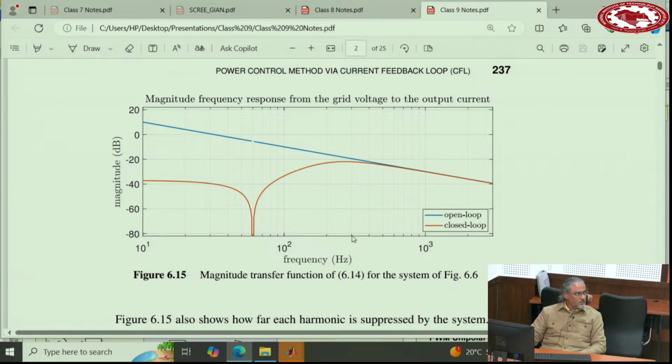300 means the fifth harmonic, which is often the first harmonic that is there. So you see open loop and closed loop are already at the same point. That means this controller does not help with harmonics, does not mitigate the harmonics. What it does is make sure that at the fundamental frequency, the grid voltage as a disturbance is removed, because we put a resonant controller there to follow the reference. That follows the reference and also removes the grid voltage as a disturbance, even though we put a feed forward anyway. The feed forward takes care of removing that disturbance. The reason we use it is because we want to have a soft start and current limiting. But the controller itself, in the long run, also removes it in the steady state.